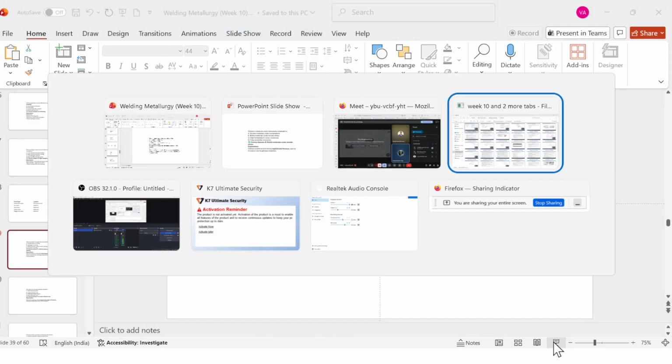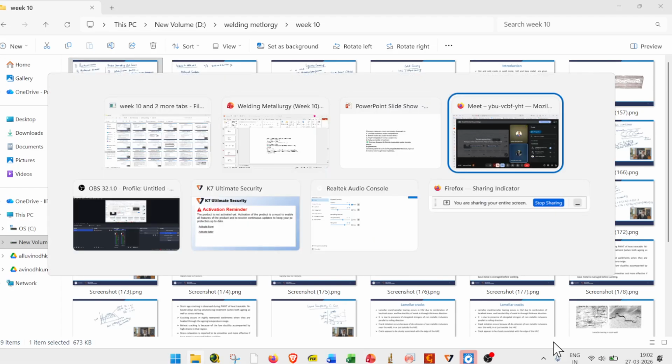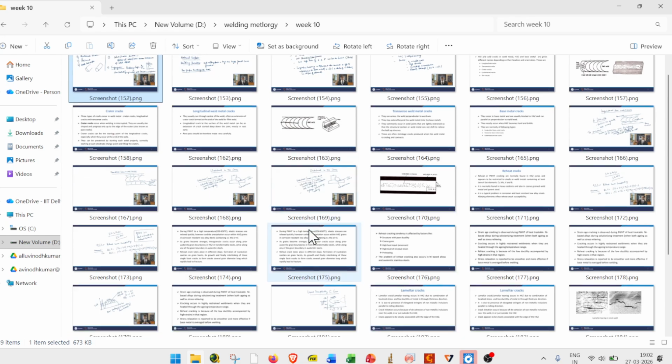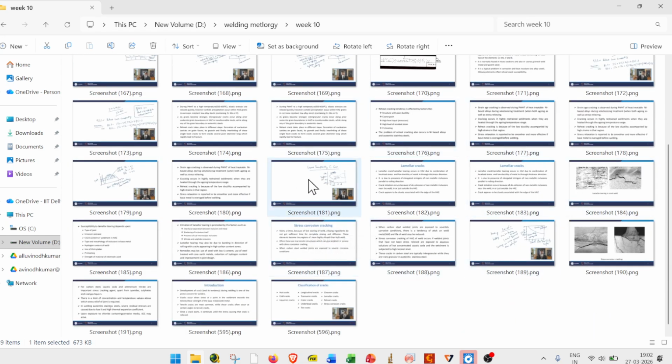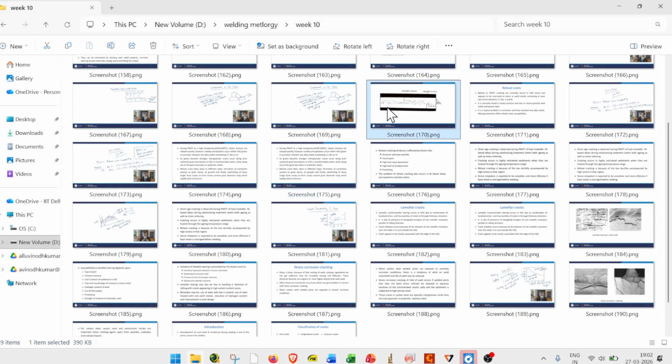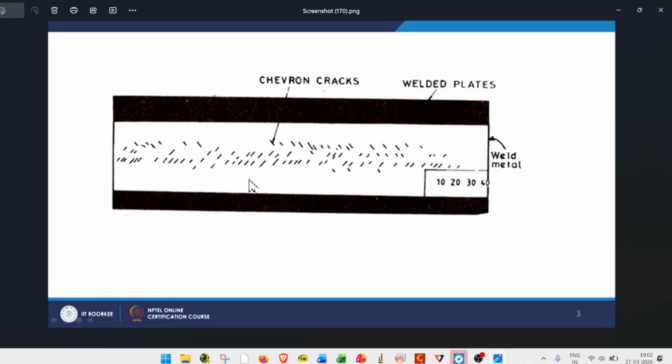So you can see here, once we weld high carbon content metals or brittle materials like tool steel, once it starts solidifying, because of this brittle phase, tensile stress is generated because of volumetric contraction taking place.